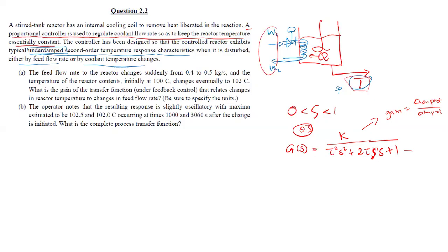And then here at the bottom we have our characteristic expression for our second order system. This will be our characteristic equation. To determine all of these variables, such as the time constant tau and the damping factor, to determine these numerical values, this is when we're going to use the different equations, such as the equation for overshoot and the time to peak.